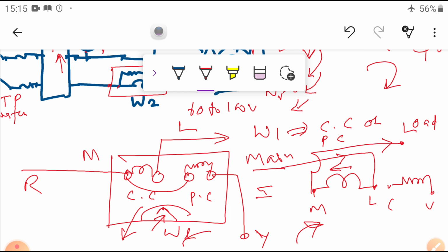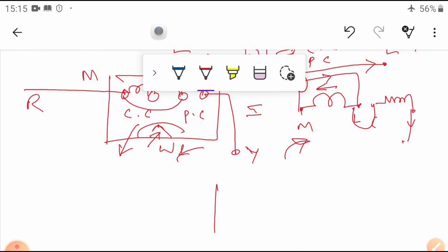So dear student, don't change both. You can change only one coil at a time. Now this is similar. Whatever is connected to the main supply is connected here, and this is connected to the V, another phase. Then what will happen? It will show a reading in the opposite direction. That is equal to the wattmeter reading. Now it will show in this direction. So whatever the value is, from 0 to this value.